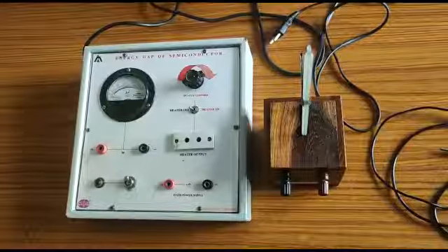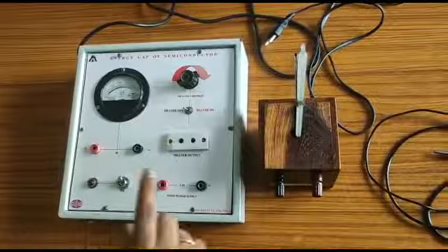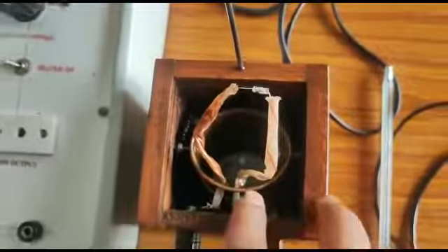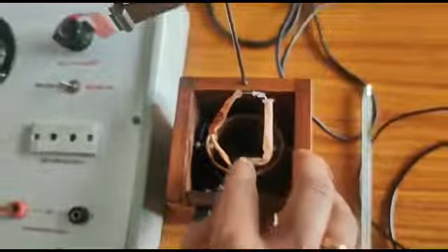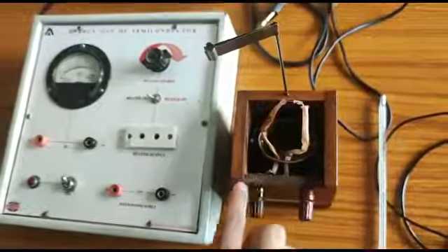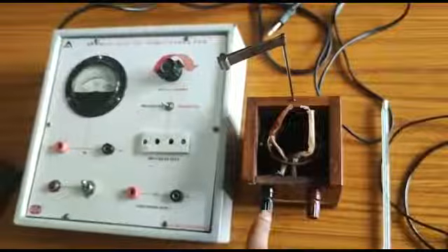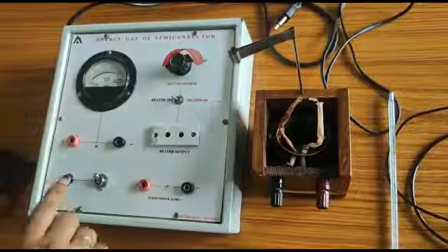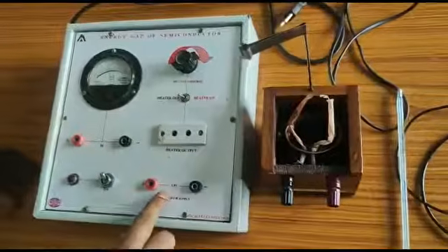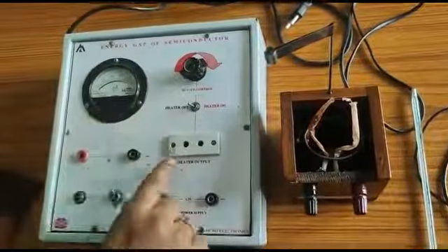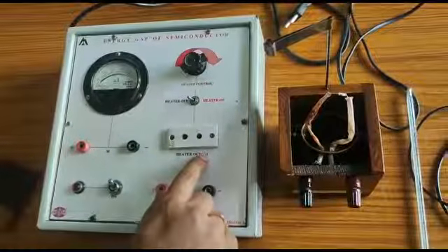We start our experiment. This is our experiment arrangement. This is a germanium diode here. Here this is a copper vessel. Inside the copper vessel we take oil, and this is surrounded with the heater. This whole arrangement we have taken in a wooden box. Here red and black indicate the two terminals of the PN junction diode. You can see in the kit three devices here: a battery, which is a fixed power supply, a microammeter, and the heater output connection plug.